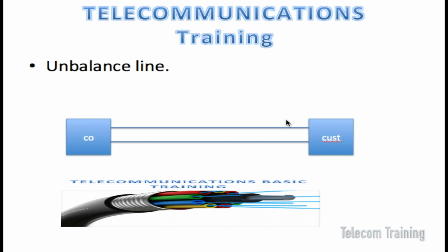Because of that, this side of the line looks different electrically than this side, which doesn't have the ground. So this is what we call a tip ground. If it was on the ring side, it would be called a ring ground, and this causes the line to look different. As a result of a tip ground or a ring ground, twisted pair technology stops working.